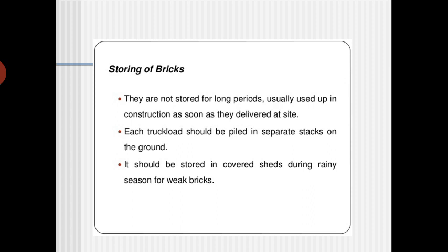It should be stored in covered sheds during the rainy season for weak bricks. Of course, why I am telling you 6 months is, after 6 months you can expect either a winter season or a rainy season. Normally in the winter season and rainy season, the damage to the bricks will be more compared to the summer season.